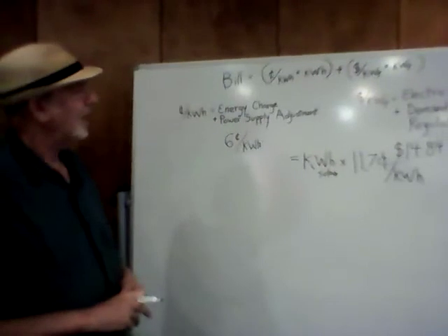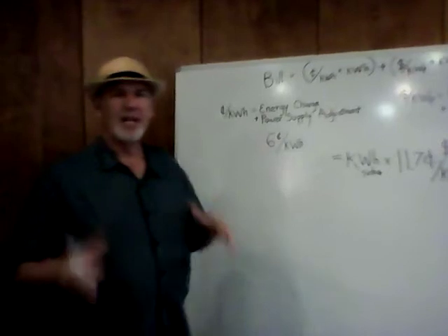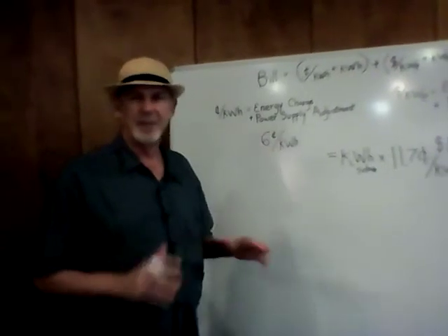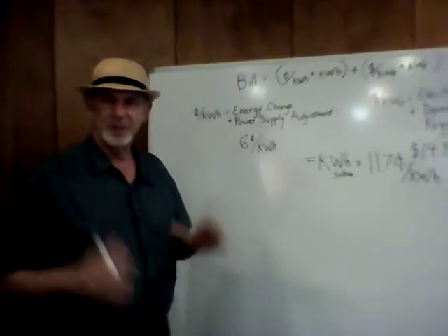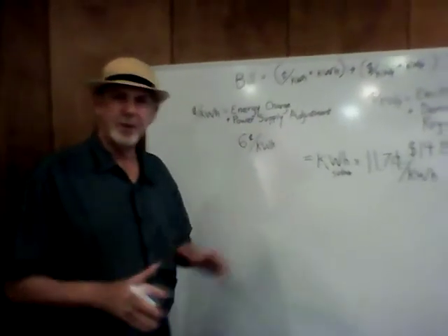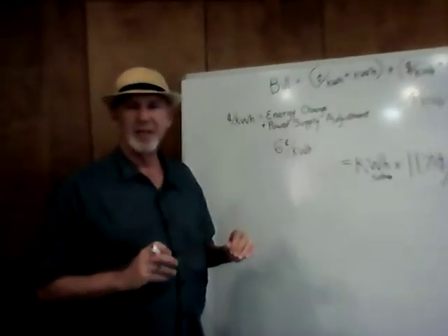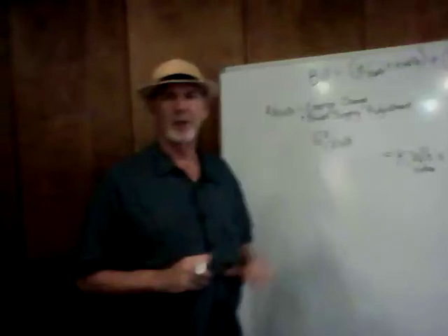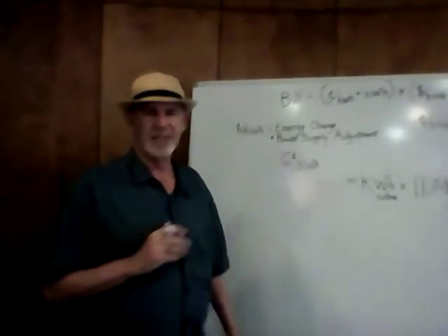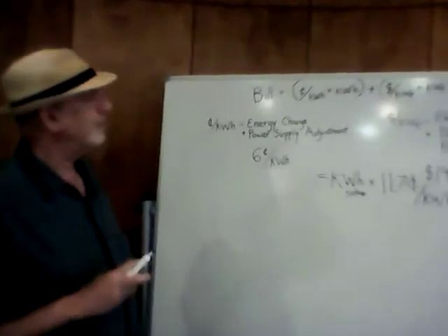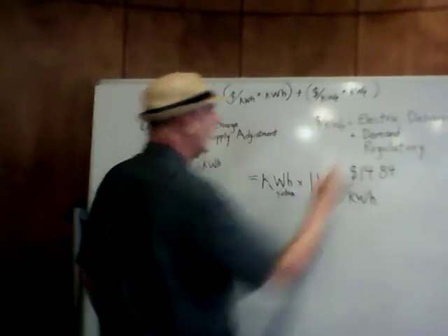Now, a little bit more complicated. Let's look at batteries. An energy storage system can be added to any building with or without solar. The two, battery storage and solar, are really independent to a certain extent, in that you don't need to have a solar system in order to see a battery go in place and save money. How does a battery save you money? Very simply, the battery will reduce this kilowatt peak.